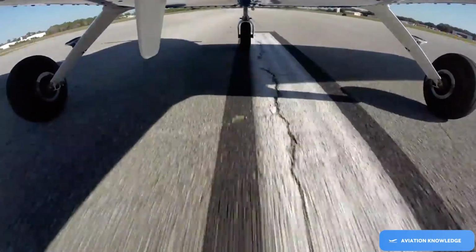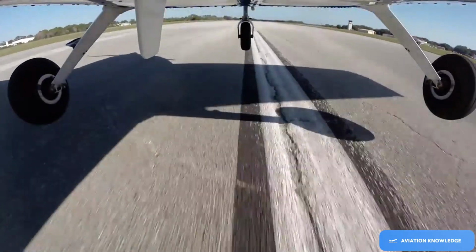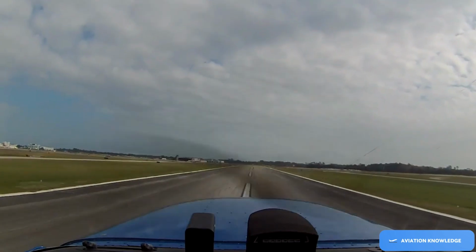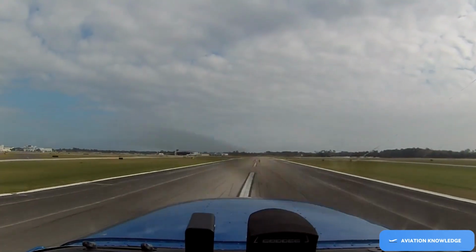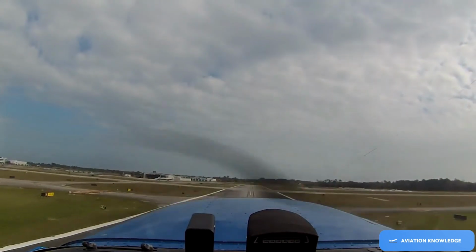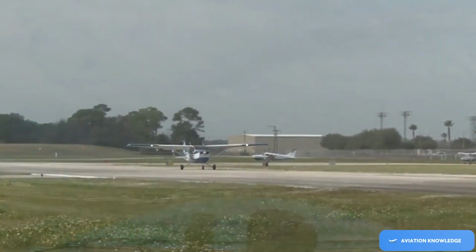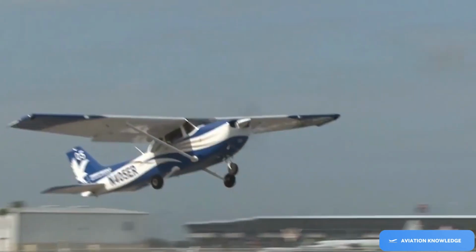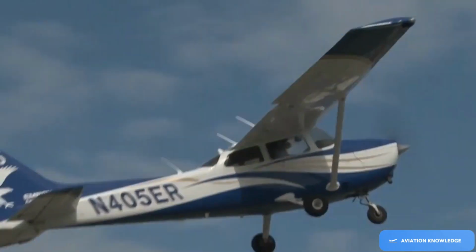A crosswind takeoff and climb is very similar to a normal takeoff and climb except for control input. Simply put, a crosswind takeoff requires additional aileron and rudder inputs in order to keep the airplane on the centerline with wings level. Crosswind takeoffs require finesse, but you'll have plenty of time to practice these during your flight training.